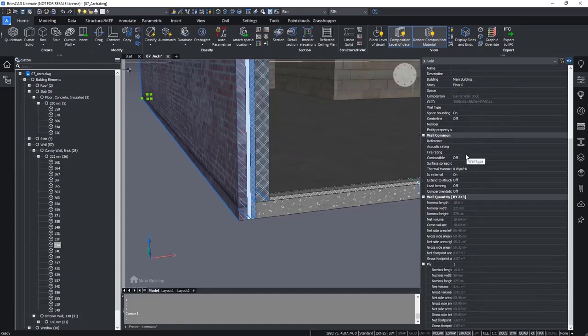Then you will have some wall common properties, which are the buildingSMART IFC common properties for walls. The IFC property sets are hard-coded and are used by other BIM applications in a similar fashion. So in the wall common properties, you can, for example, find fire rating, acoustic rating, etc.